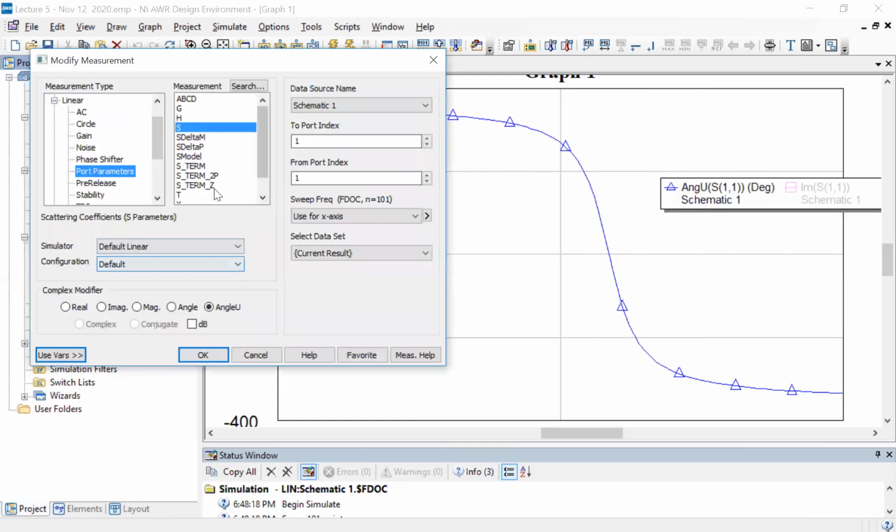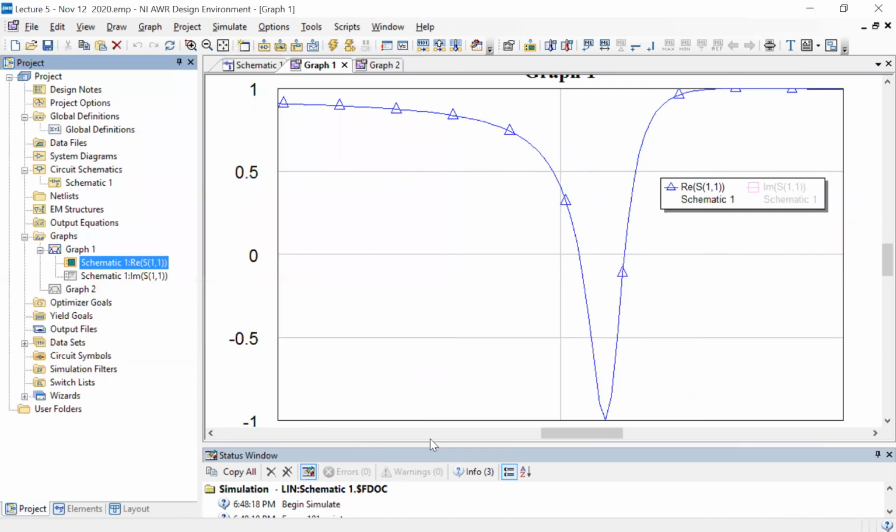We can look at the real part instead. And here you will not be able to do the unwrap business. But what you can now see is the effect of the capacitor as a 180 degree phase shift in the real part. Normally the resonance had things going from -1 to +1 and coming back. But here it goes from +1 to -1 and then goes back again.